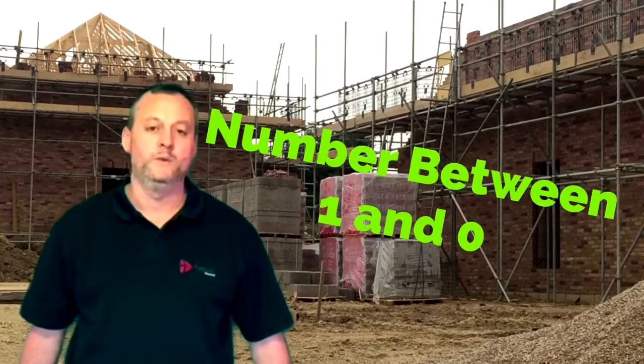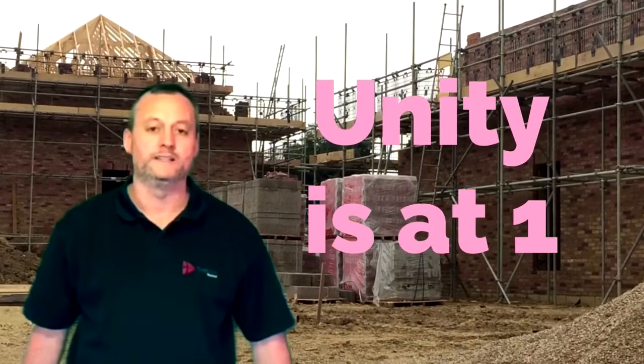We went on to work out simple calculations for power factor as well. We worked out our power factor in 3 ways. We did true power over apparent power. We did kilowatts or watts over kVA or VA. And we did resistance over impedance. Again, it would be lovely to remember all 3, but worst case scenario is to remember power factor will be a number between 1 and 0. Unity is at 1. We like to leave our lagging power factor of say 0.8, 0.9, etc.